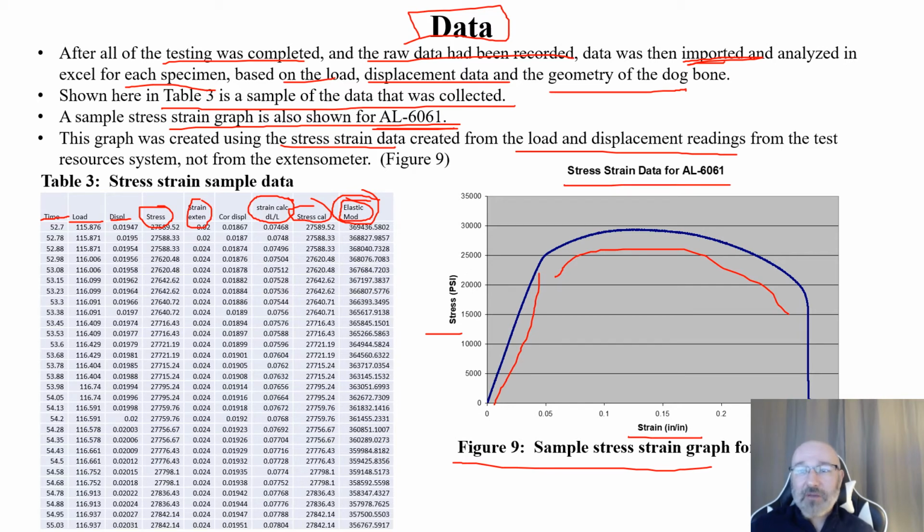I wanted to look at that first because I can look this up. I can find this exact stress strain graph for aluminum 6061 and double check that this is accurate, which will let us know, first off, is our setup correct? And second, did we actually have aluminum 6061? And did we have a good specimen of that? Did we have any work hardening with that there? So all that information we can use in order to double check our calibration, double check our test specimen setup for these tests based off of a known material.